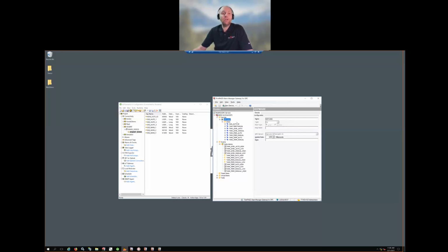Once we've built that connection to an OPC server, then we can subscribe to tags, or as we call them, items in the software. We do that by clicking on a new item here, and we can click on the Browse button, and we can display any of the tags that exist in that OPC server that we've selected. So you can see if I dig through the SeQent configuration here, we can take a look at the tags. The only reason I've got Kepware open at all, Kepware being one of the OPC server examples that we can connect to, is that, as I said, we are an OPC client, and so we could connect to any OPC server. But you'll notice that we're showing almost the exact same instances.